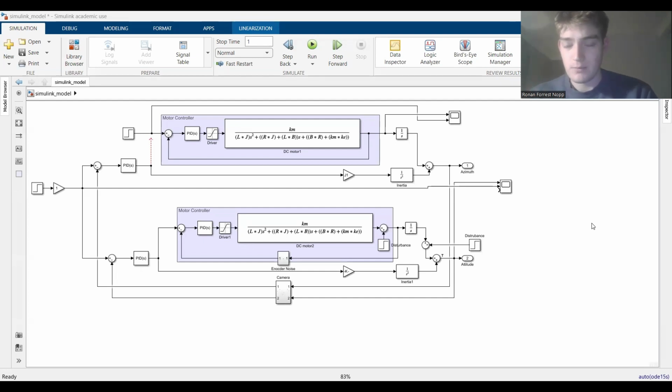Without getting into the implementation details too much, it will just use OpenCV to track the centroid of that bright spot. And since the camera is distortionless, the deviation of that centroid within the camera's field of view maps linearly to the angular deviation between the gimbal and the target. I'll talk more about my camera plant later.